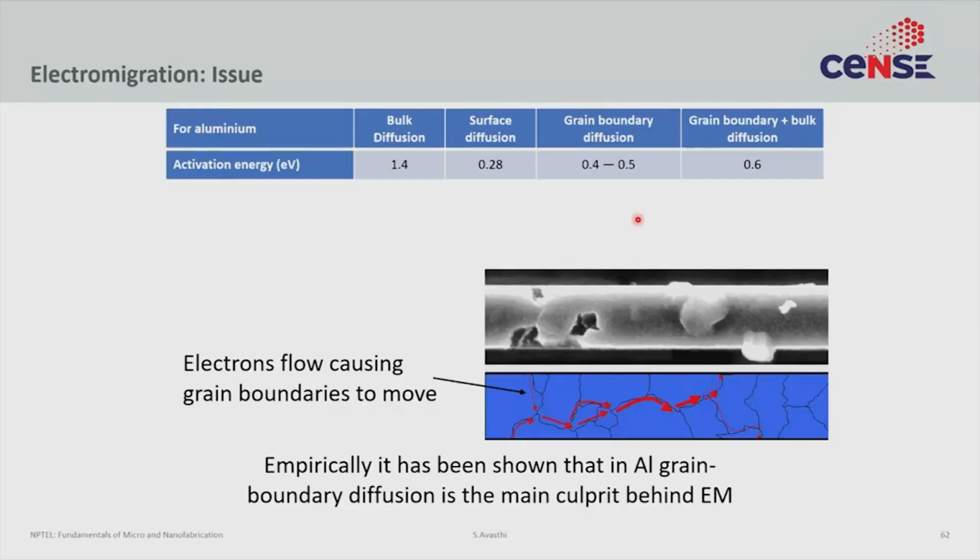So, this was a huge problem for reliability, because even though your silicon is very reliable and the devices are very good in complicated circuits, with time the metal lines would degrade, the delay of the line would increase, or they would just fail, which would mean the devices would fail. So, this is the issue, right. The issue is aluminum is moving.